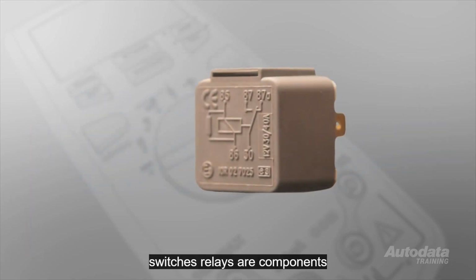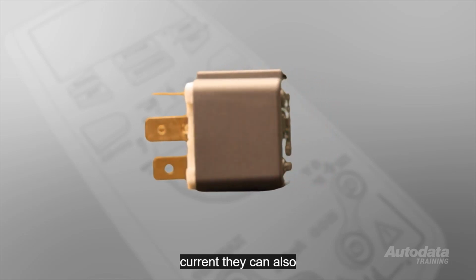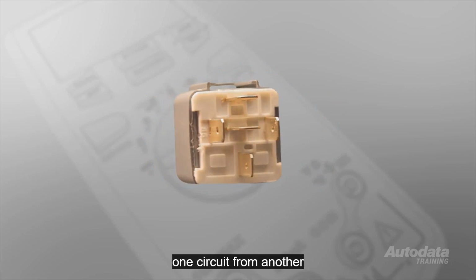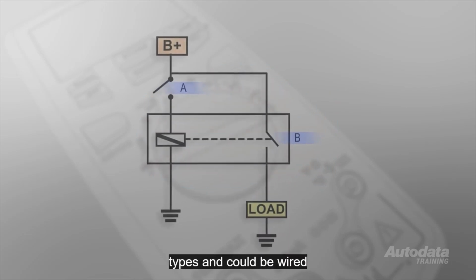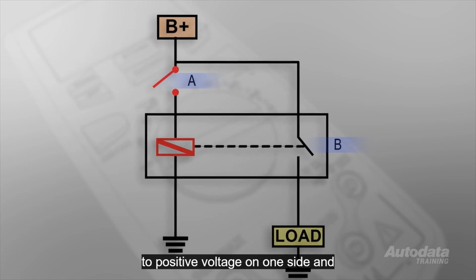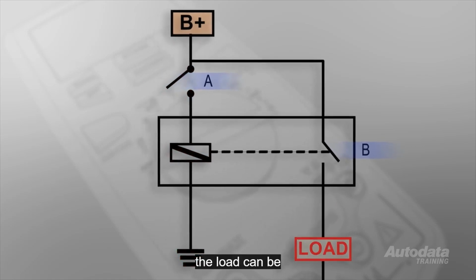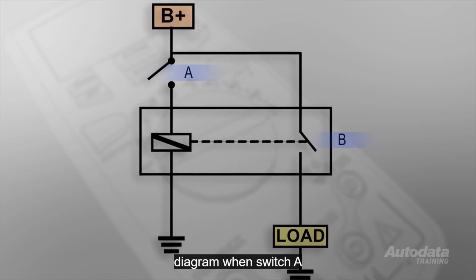Relays are components that use a small current to switch a much larger current. They can also be used to electrically isolate one circuit from another. The 4-pin relay is one of the most common types and can be wired in one of 4 ways. The coil of the relay can have a switch to positive voltage on one side and a ground on the other. The load can be positively switched with a permanent ground as shown in the diagram.